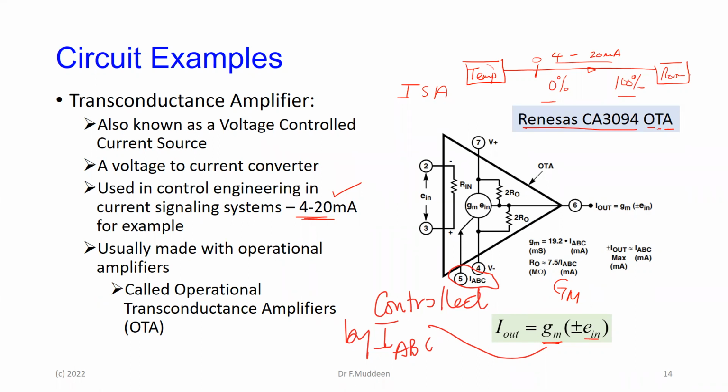So what they did is that 4 to 20 is an odd number, and that has some historical reasons. When you're doing controls, you'll see why they actually selected that, but they don't use 0. So if you do get 0, then somebody knows that the communication line between the temperature sensor, whatever the sensor is, and the control room is at fault. Once it's operating, you're going to get somewhere between 4 and 20. If you get less than 4 or down to 0, then something isn't working.